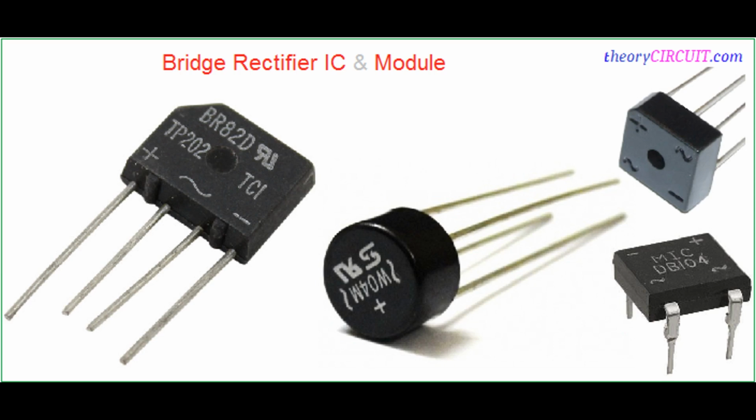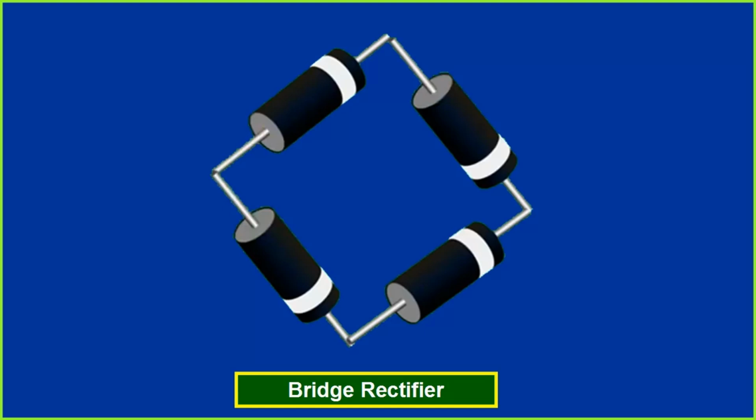In this state, the diode acts as an open circuit, preventing the negative half of the AC waveform from reaching the output. The output of the half-wave rectifier is a pulsating DC waveform. It only contains the positive portion of the AC input voltage, while the negative portion is completely removed. The output voltage is not constant but follows the shape of the positive half of the input AC waveform.